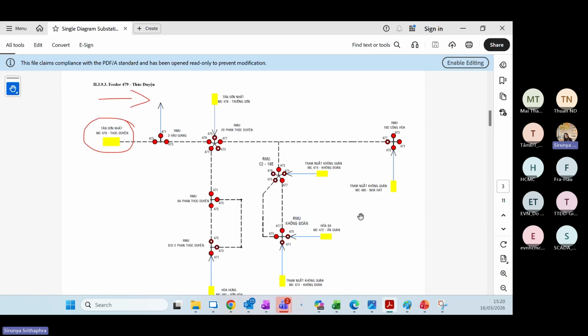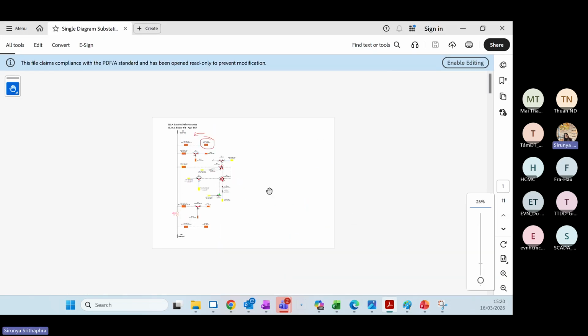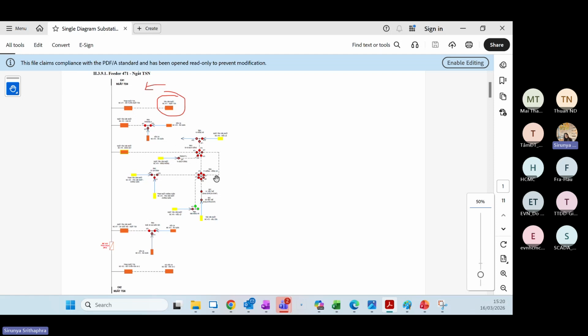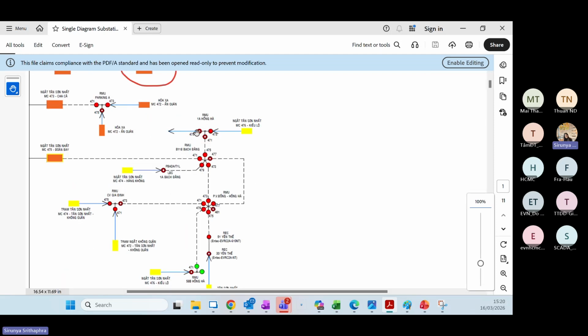And for feeder, you go with the one that you mark the NO, right? How about this tie switch, it should also be open to be normal. Yes, tie is open. How about the green one? Is it the hollow thing? This is hollow inside, so normally open, right? Yes, this is the symbol for normally open, the hollow one.